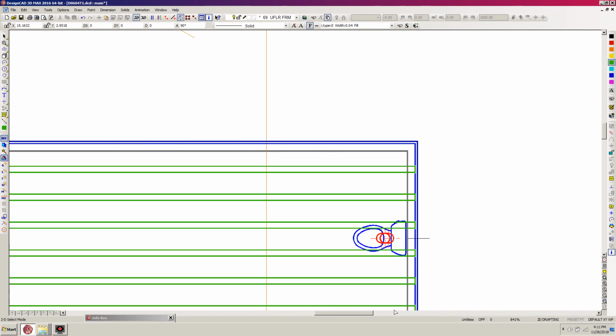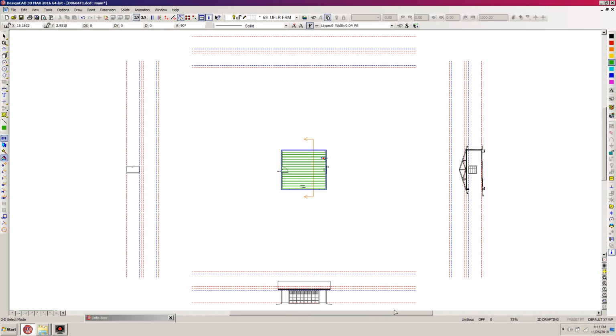So that means that just by changing our layout from one side to the other, we were able to avoid doing any headering off for that toilet's water closet flange. So that's kind of a good thing. Okay, so now we have our joist basically laid out,